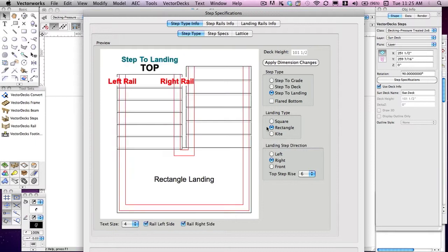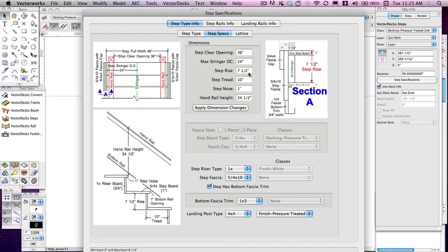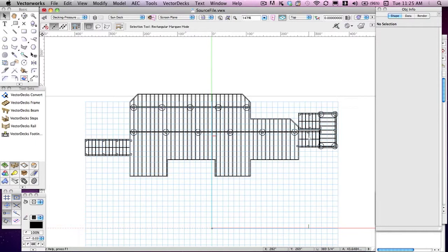And let's adjust the steps to more equal distribution. My specs also show mathematically for that to work, to be that 100.5 inches, we need to have that step rise to be 7 1/4. So let's apply that right now. All right, that's done on that side. Now this side's going to be a little different. It needs to be that 70 inches, and we're going to adjust that later. I'm going to first finish the drawing, and I'll show you what we'll do just before we save it.